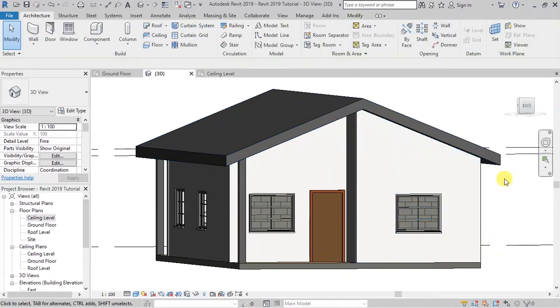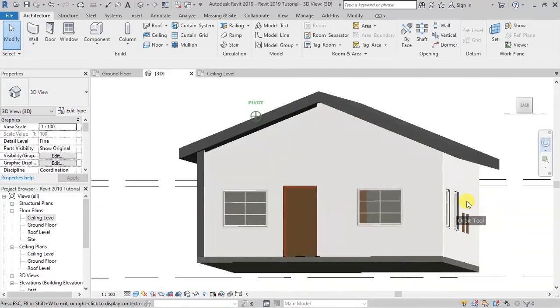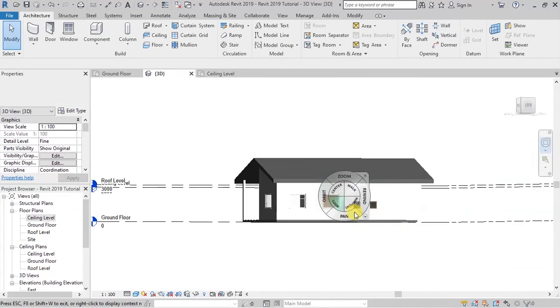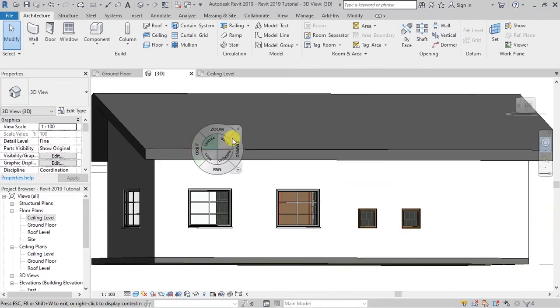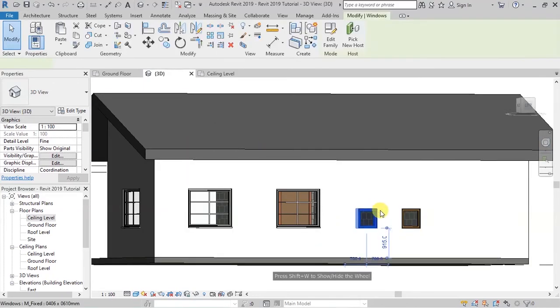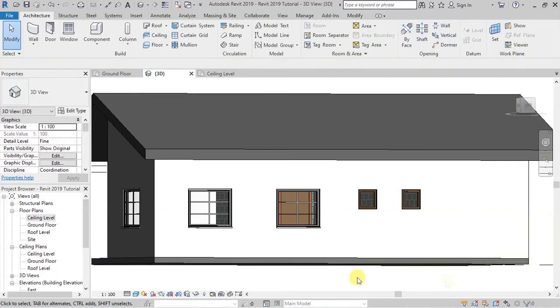So that in this case, if you try to orbit, you have our walls moving up, well connected to the roof. Then if you look at these windows here, I think they need to move up by, let's say we could have these as 1200. Let's have 1500, like that. Then have these as 1500 so that it moves up the same height as the other walls.